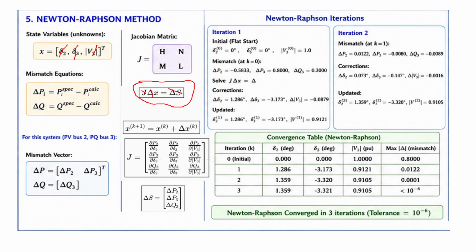So considering this, it's very easy and straightforward to obtain the magnitude of the parameters after several iterations using both Gauss-Seidel and Newton-Raphson. But what makes those two approaches different is that Gauss-Seidel is used for linear systems, and Newton-Raphson is very important for obtaining solutions of nonlinear systems, specifically for a power system. You see, the change in mismatch, like power and voltage angle, and voltage is nonlinear, so it's very useful for such types of equations.